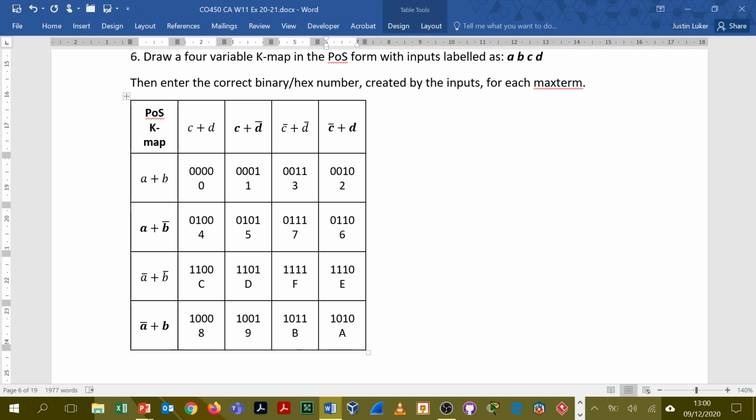Make sure you're familiar with the input pattern and how it changes from one square to the next. You can draw out these Karnaugh maps this way, because if you're going to answer the questions in TCA3, for example, I'm assuming you know how to draw a Karnaugh map, and you can draw the inputs in the same way as I'm drawing them here, numbering the cells the same way as well. It's really important the cell numbering is correct.